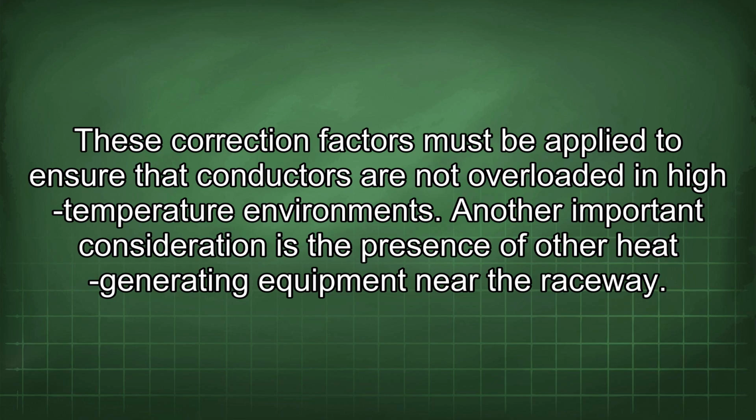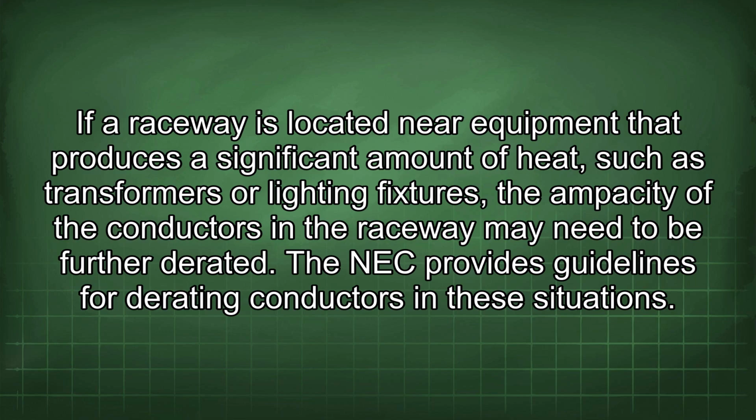Another important consideration is the presence of other heat-generating equipment near the raceway. If a raceway is located near equipment that produces a significant amount of heat, such as transformers or lighting fixtures, the ampacity of the conductors in the raceway may need to be further derated. The NEC provides guidelines for derating conductors in these situations.